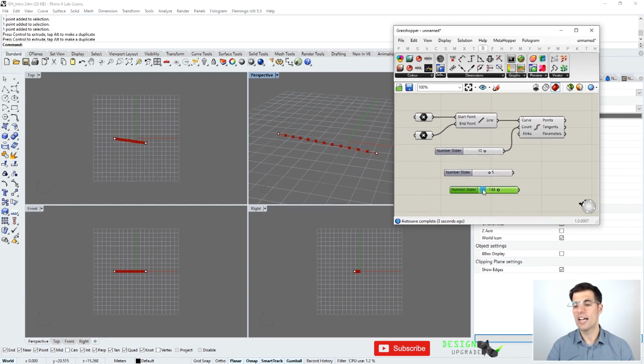And we can even select, let's say, a default value. If we say, for instance, 2, 3.5, so the default value is going to be 5, and then 3 points, and the maximum value, in this case, let's say 8. So the default value is 5, and it goes between 2 and 8. Just another way of defining our Grasshopper sliders.